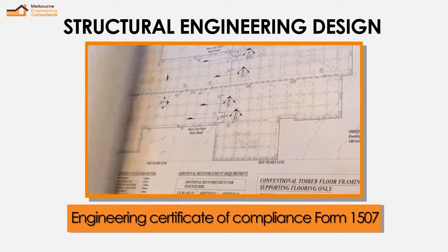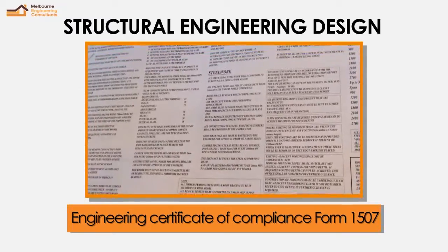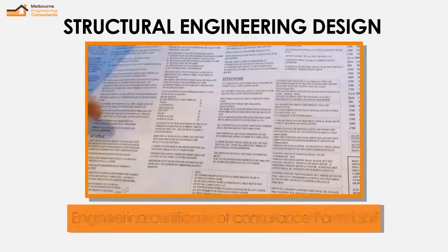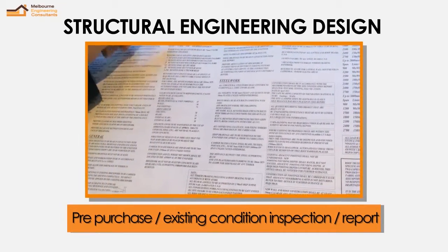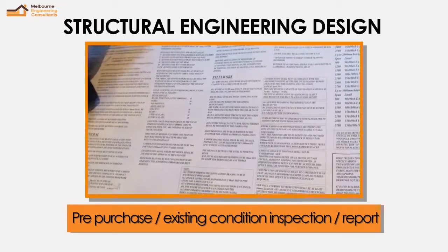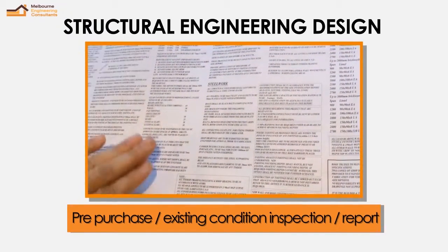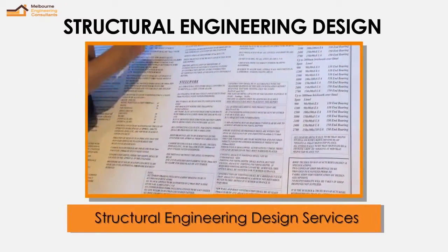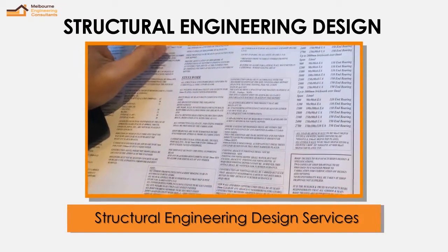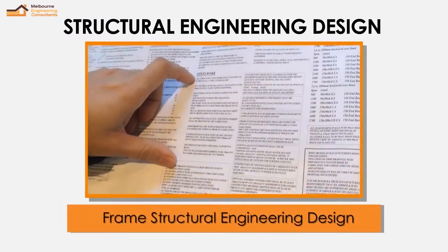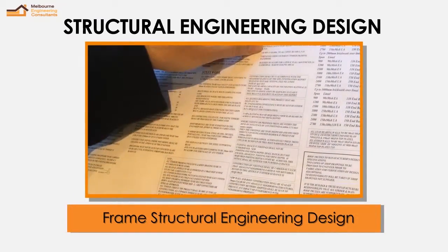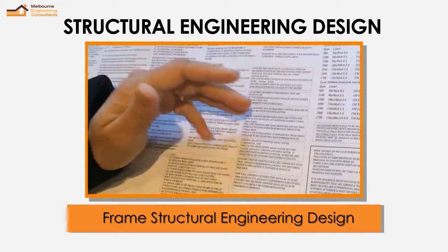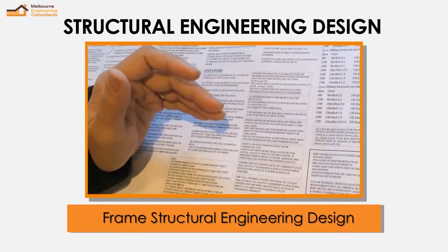The first page is showing a note which covers all the requirements for the site construction, including the site preparation. Secondly, the footing notes, the concrete grades required individually for blinding concrete, raft, strip footing, and so on, and the required ground covers for the reinforcement. The other notes are the footing founding depths, steel work quality as per the Australian standards, framing notes, general notes for the soil, notes for the root barrier, and so on.